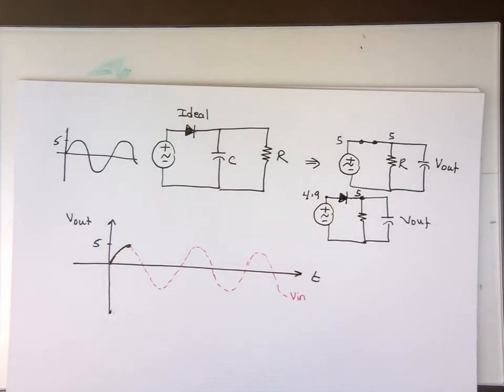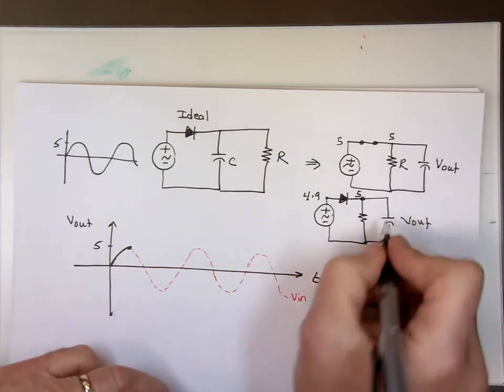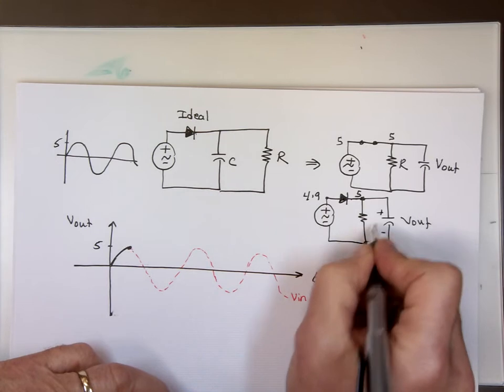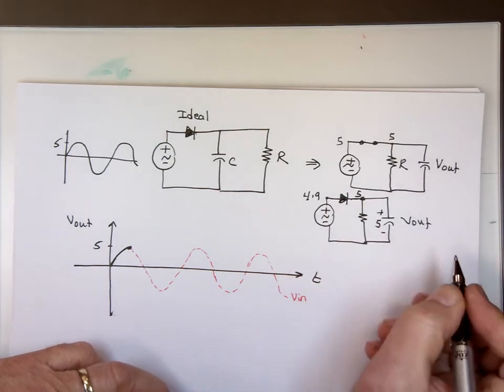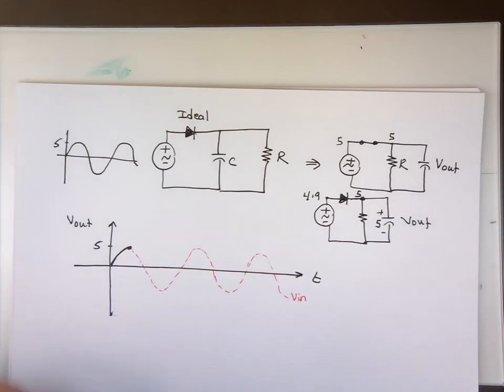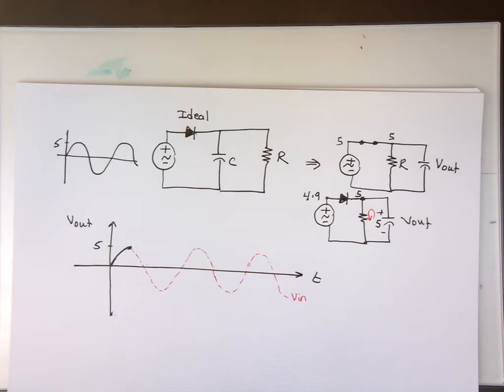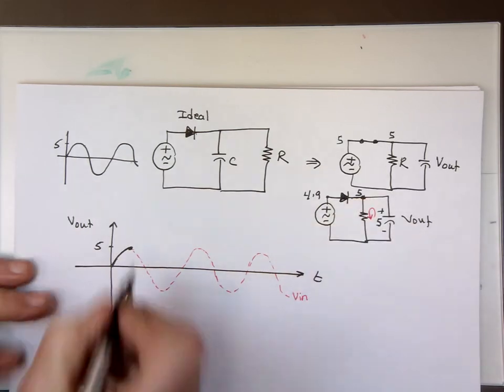The problem is that voltage across this doesn't remain the same. This actually is charged here to be 5 volts at that time. So this becomes like a source going to force the current to go this way and start to discharge. So this will go this way and start to discharge, which means that voltage will start to drop down and will go like this